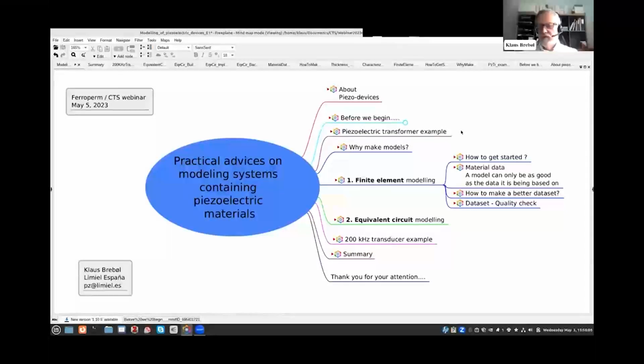fatigue is a difficult problem. I guess you can also see a certain spread in parameters there. I mean, I have a certain experience with fatigue in metals for high power transducers. And for instance, if you buy the same titanium alloy from the same supplier, but it has been machined in different ways, you will see different fatigue behavior. So I think it's quite a can of worms that you are opening if you begin to do this. So yeah. Good luck. Yeah, good.